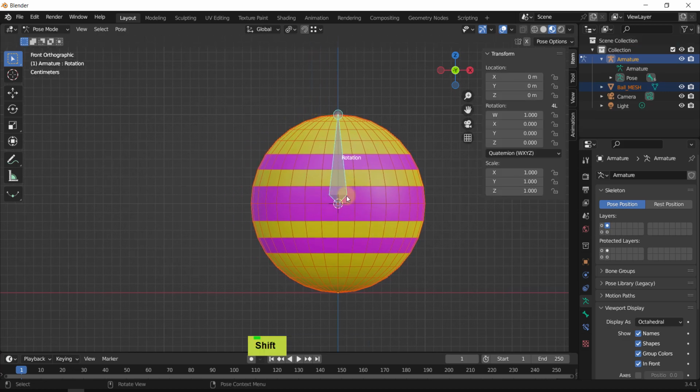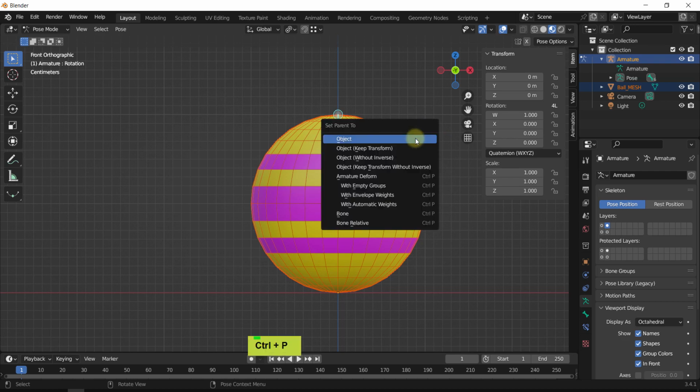Okay, don't forget that this is just a single bone that's visible, but in the armature this is a bag of bones. We have way more things. So this is why you have to highlight the actual bone you want to build a connection with the sphere. And I'm using Control P, and that brings up Set Parent. Now we can use deform and other things, but here this is natural, there's no skinning involved. This is just basically a copy position, copy rotation, copy stretch. So whatever the bone does, the ball will do the same thing, and that's it.